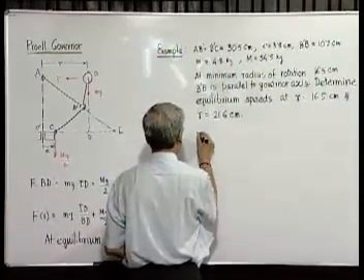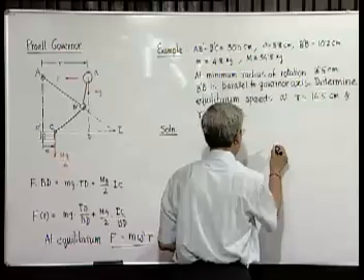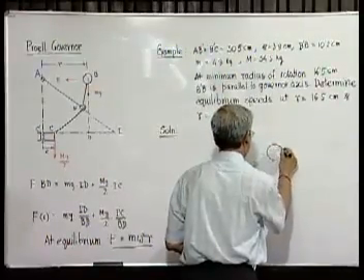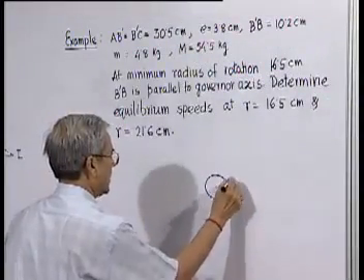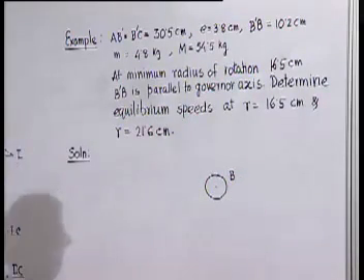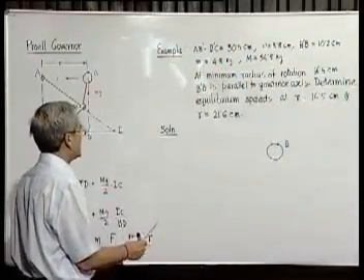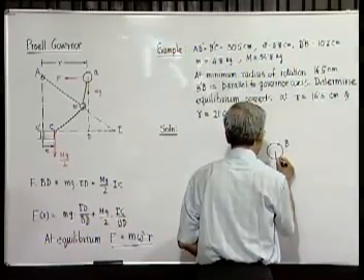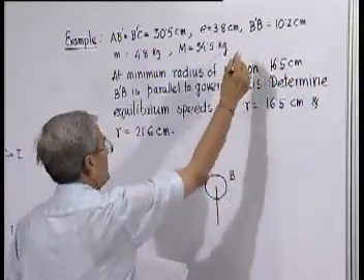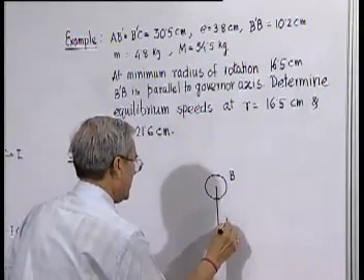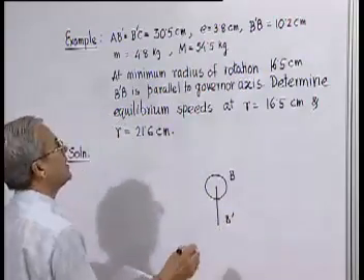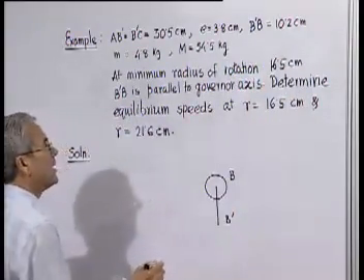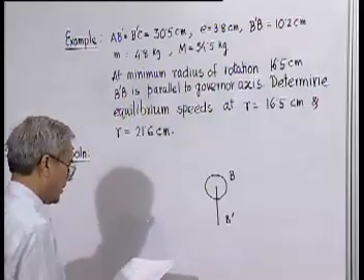To solve it, first we select any point as the center of the ball. Since we know that B prime will be vertical, that means parallel to the governor axis in this lower position, we draw a vertical line whose length to point B is given. B prime is given because this length is 10.2 centimeter. So we can find out this point.